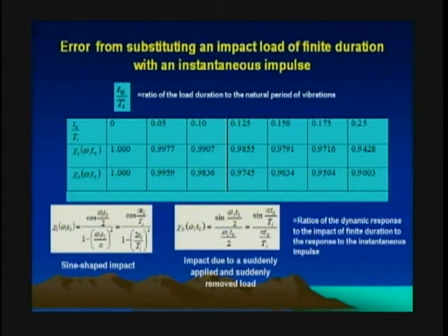By the way, I want to indicate that a quarter of a period has a very important physical meaning. It means that the system needs a quarter of a period of its vibrations to be deflected from the equilibrium position to the maximum displacement, where the maximum amplitudes and the maximum stresses occur. Therefore, a quarter of a period is a very important characteristic of vibrations. That's another important thing that we will discuss a little later, but in this connection I want to start talking about it right away.